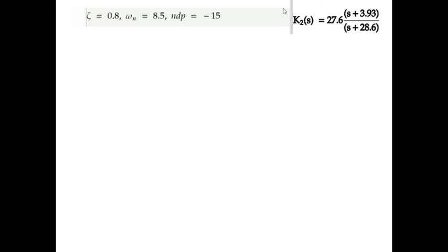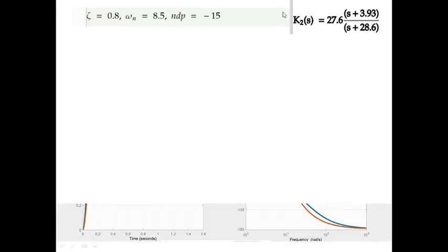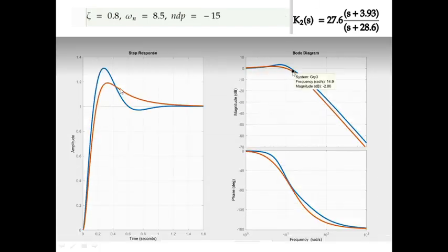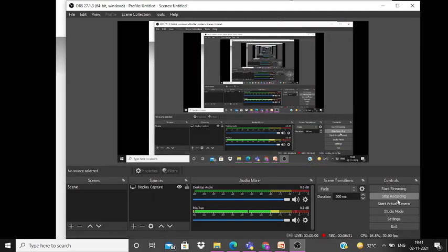So we get the new controller and we have the plant. We do the Bode plot and we get this result. Our overshoot has been reduced, our rise time has increased to some extent, and the bandwidth is more or less the same, and we get that the M peak has reduced. So this is a good solution. We'll discuss the other aspects in the next video.